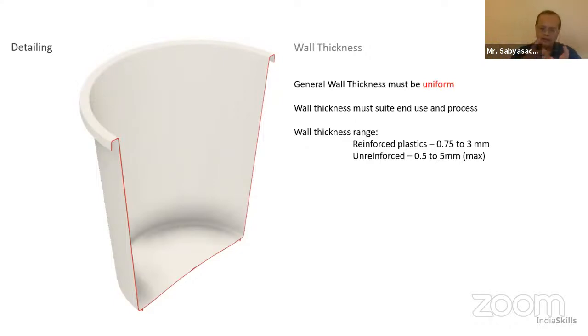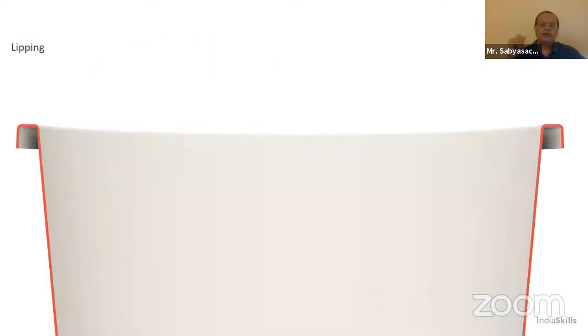You have a drill bit or a machine drill, a motorized drill. So there, you might use a reinforced plastic because it's taking a lot of stress and strain on the component, and it might have nylon filling. It might have glass filling and in nylon. There the wall thickness can go up, say about 2.2 to 2.5. So this is something that, with experience, you have to study. You have to pick up that if this is my application, this will be my wall thickness range that I'm doing, right?